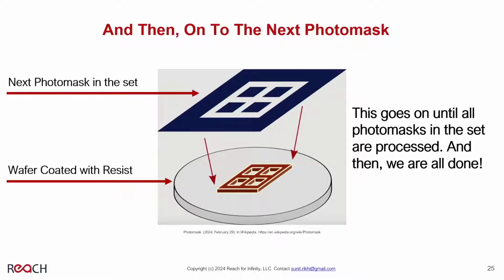So now we move on to the next step. Then the next step is to insert the next photomask, go through the same process again, and go on and on and on until all the photomasks are exhausted. And what you got? You got a processed wafer. Hundreds of thousands of dollars worth when you started with something like a 6,000 or less, actually a lot less. But a processed wafer that yields all these die, you've created a huge value by going through this process.